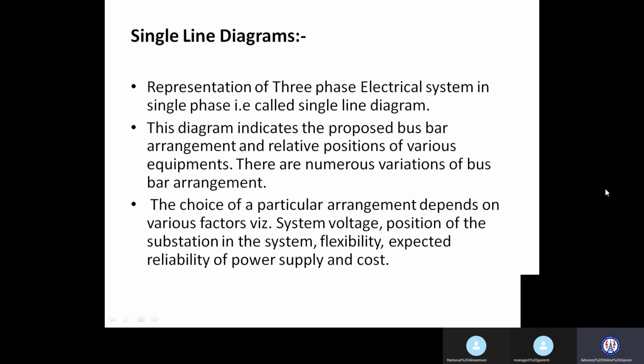So now your incoming feeder voltage rating is 33 kV. Your outgoing feeder voltage rating is 11 kV. So what fault current are you going to consider for the incoming feeder and for the outgoing feeder? Incoming feeder is 33, outgoing 11. So for the incoming feeder fault current you are going to consider 25 kA, and also for the outgoing feeder you are going to consider 25 kA. Understand, Hamid and Ganesh, how you are selecting?